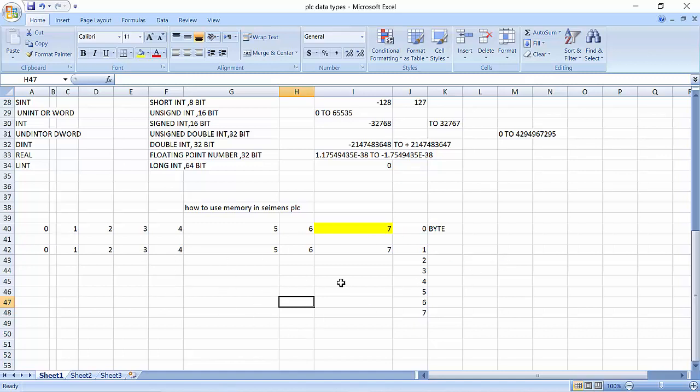One more thing I tell you about memory addressing, the kinds of memory. One is M, so when we write here, for example M0 or M1, M2, when we use the internal memory, we have to give that address same like 0.0, 0.0. Also this one M1.0, M2.0. Same addressing, bytes increase to the downside, however much memory you use.